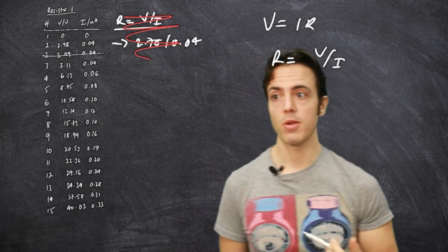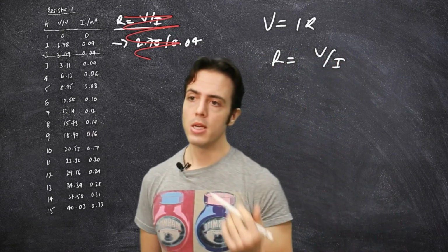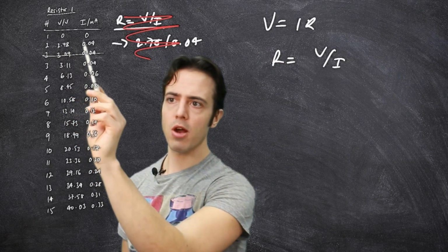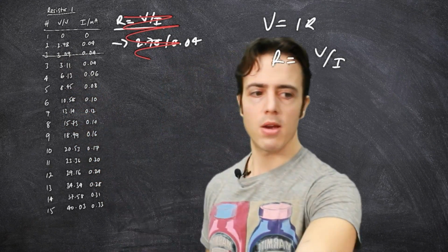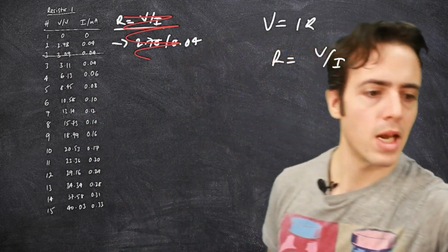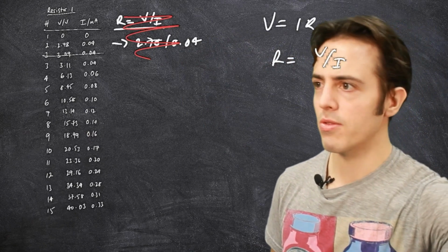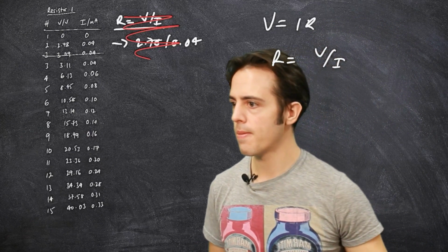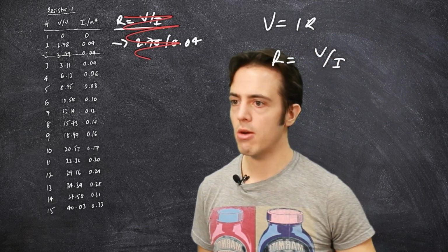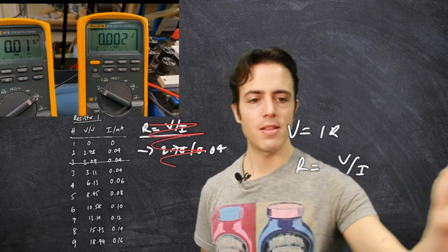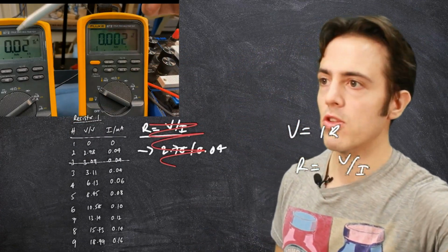That's not something that we do with this sort of experiment, because when we first powered up, we assumed we had 0 and 0. We actually saw that when I've got nominally no voltage going through here, there's no power into this breadboard, there's some sort of, let me just bring this back up. So even though I've got nominally no power going into this whole system, it's still registering a small voltage and a small current.